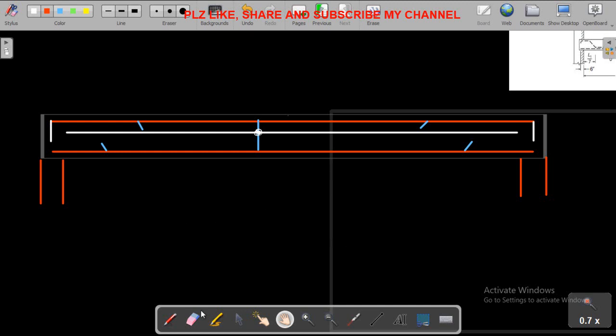So this is my diagram, this is my supports, and make sure that this bar should enter right inside the wall up to a distance of 6 inches. These are my top bars, which is 2 number 4 bar, just to hold the stirrup.